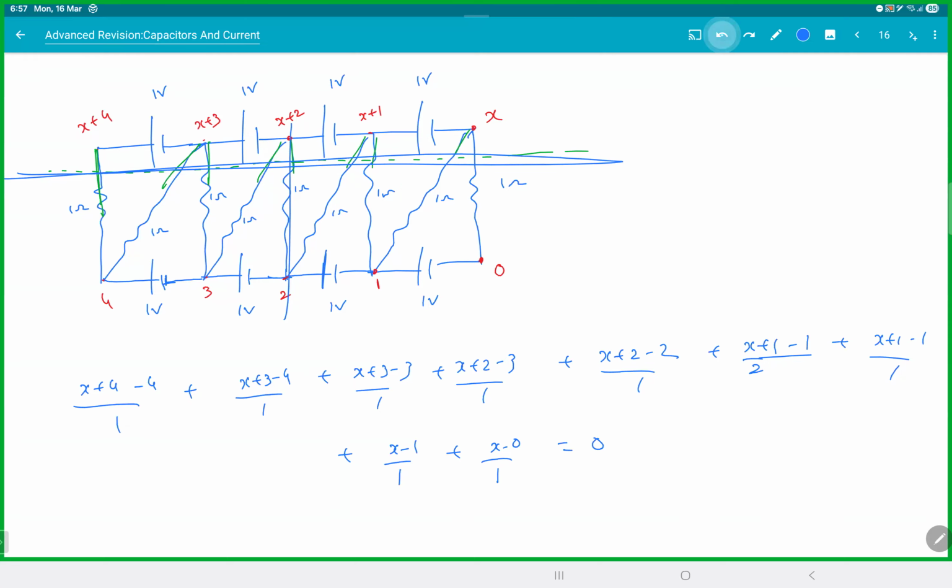So eventually what would have happened? Think about this. If the current is just flowing in one direction, won't this point become negatively charged and this become positively charged? Is that making sense? That means whatever current is entering the line must be crossing back somewhere. We don't know where. It is simply charge conservation. So you can apply nodal analysis not only for one node, but for 10 nodes together. Are you clear with this?